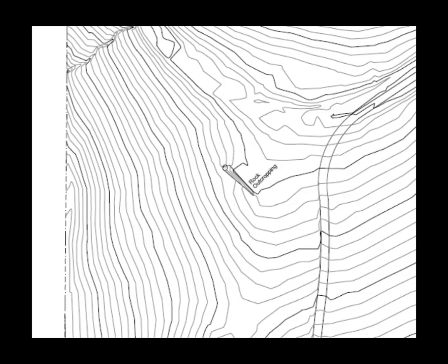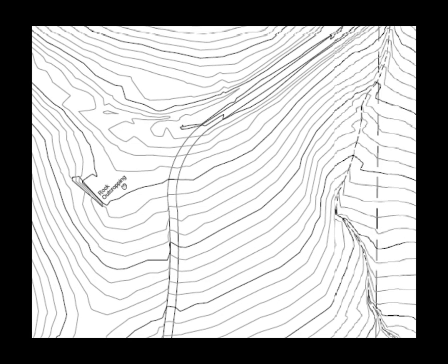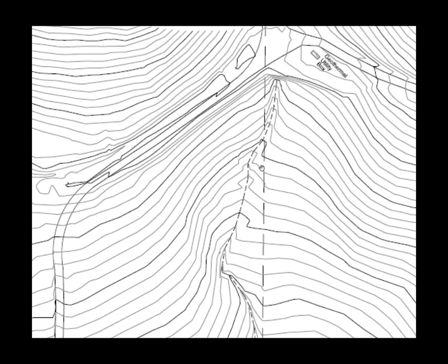They did kind of just a rough outline of the rock outcrop, but it was preserved. Then the stream does have a break line in it, so you can see the contours pretty well V into the stream appropriately. The cut bank, the contours should be parallel running along this uniform cut bank, and they're not, but again, with a 25-foot grid, you're not sampling it very well.